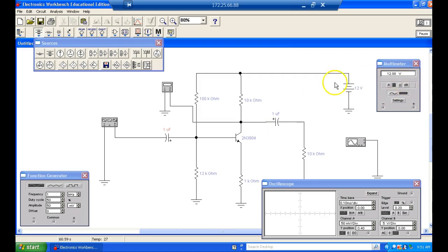So I come over here, I measure 12 volts over there. I come over here, I measure 0 volts over here, or microvolts over here. Then I know I got a problem. But this is one of those two scenarios right here. So what caused this to happen before? That 100K open, so my 100K could be open, or my input capacitor could be what? Shorted. So you got two things that could happen. All the other things, we knew exactly what it was. But this right here, this would be two things that could be wrong. Right? That makes sense? Are we okay?